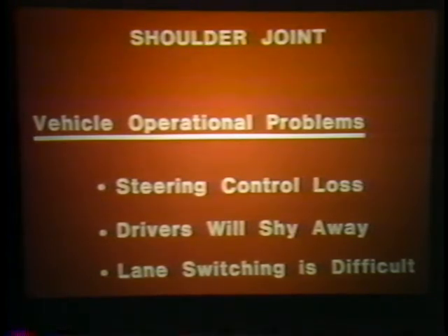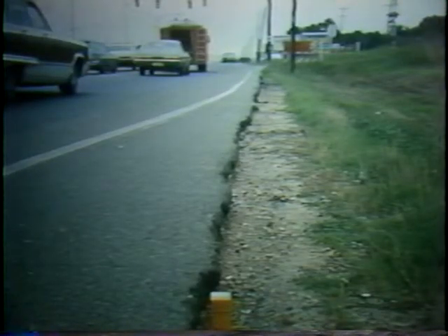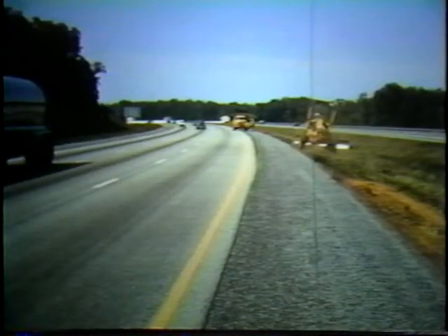Both conditions adversely affect safety. The shoulder itself can deteriorate, and shoulder deterioration at the outer edge is a warning that the deterioration will progress toward the travel lane. Water erosion under the pavement and vegetation destroy the base material that supports the surface. Water can't drain away from the shoulder if soil and debris form a dike at the edge. Water then permeates the road base.